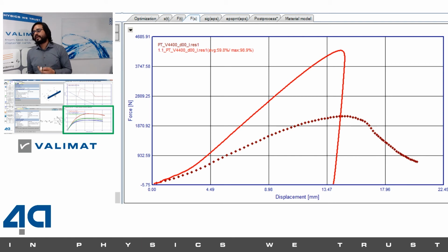And there is one thing that is clearly evident from this model: at the beginning stage, the material model represents the test curve quite well, because that is the bending dominated area and our material card is derived from bending. But in a higher strain regime, we go far away from the actual curve. That is because we do not have any sort of tension compression asymmetry in the model, which is required to actually model this more accurately.